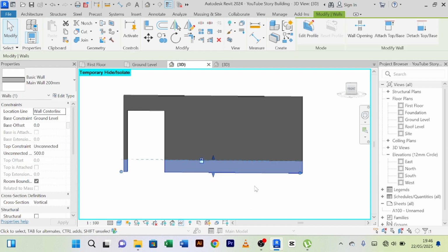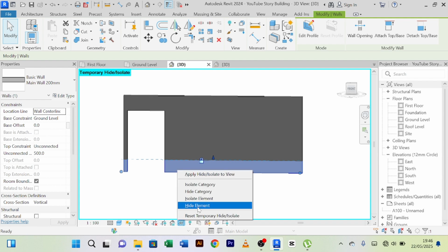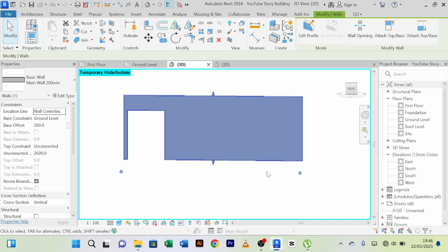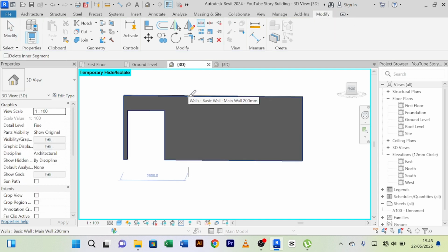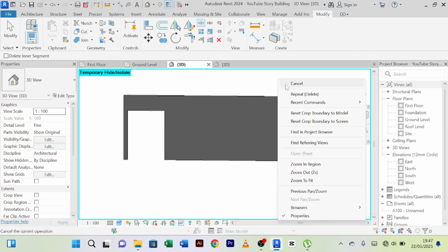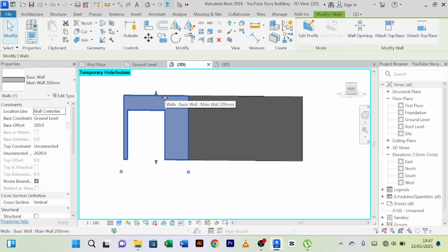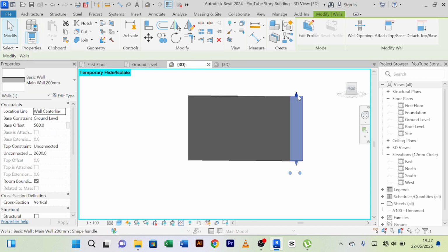So from here you come to your architecture. From architecture you go to your wall, you say wall architecture, and you click on this drop down, and you scroll down to almost the end, and you'll see here curtain wall empty, curtain wall exterior glazing, curtain wall storefront. What we want is this curtain wall. You can use any of these, but we want to go with this curtain wall which is completely empty, because we want to know how to even create the grids and the mullions.